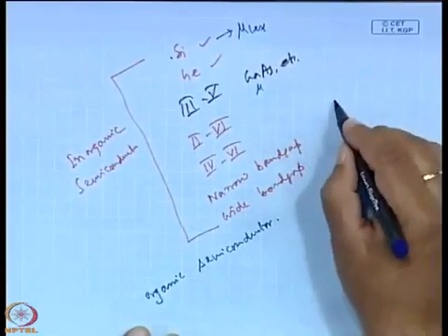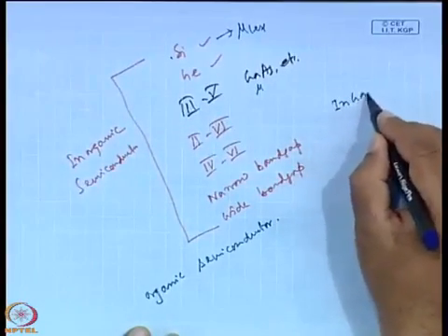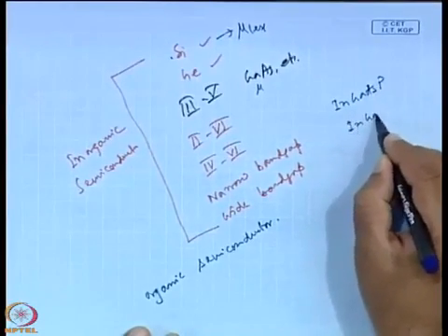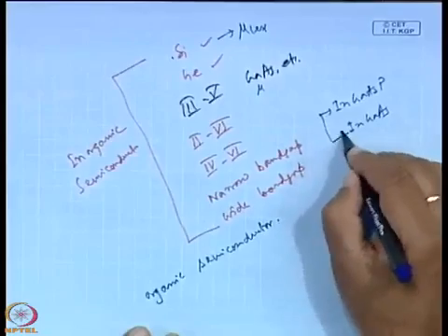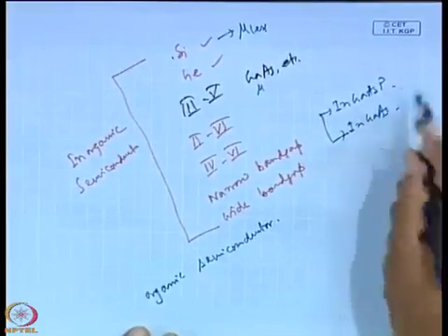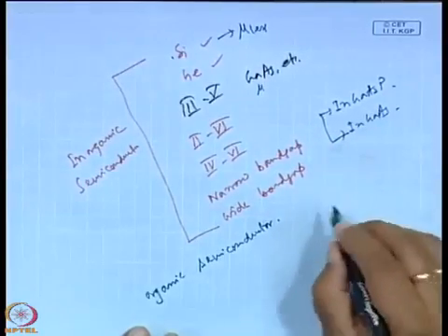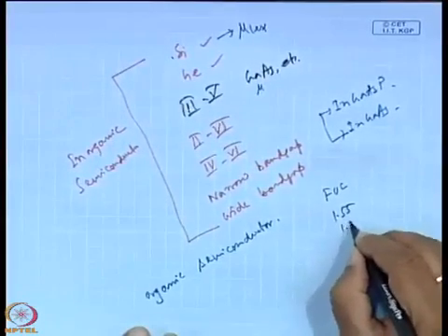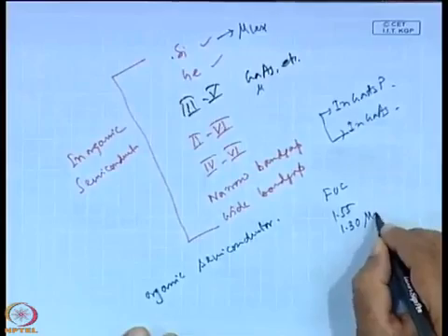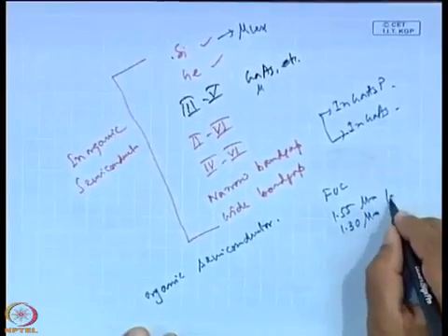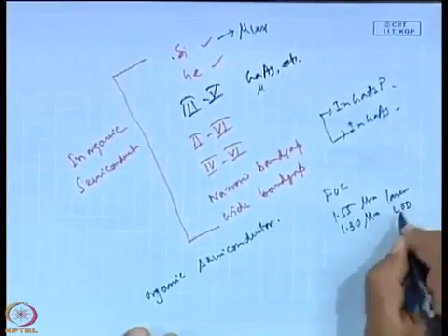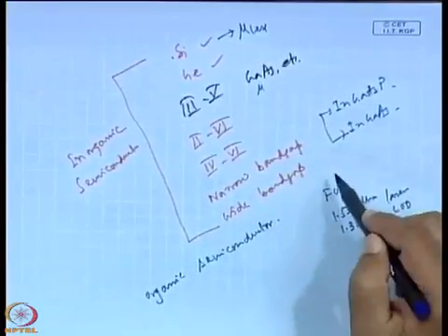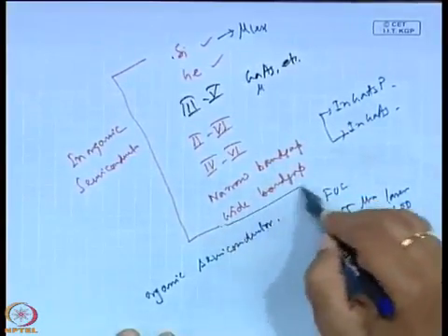Then we talked about indium gallium arsenide phosphide or indium gallium arsenide. Those are also 3-5 based semiconductors, but ternary or quaternary. These are used for present-day fiber optic communication for making 1.55 or 1.3 micron laser or LED for fiber optic communication.